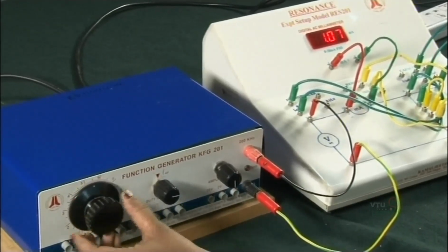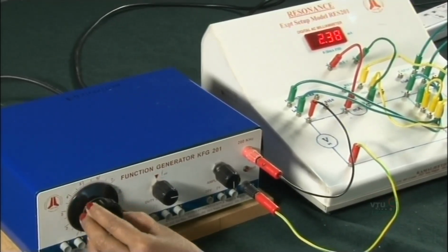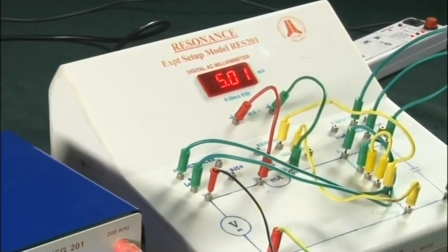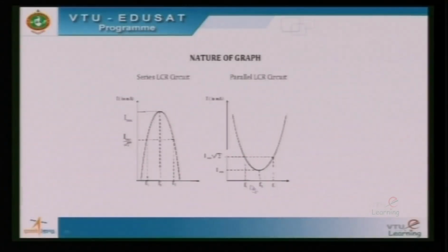As you increase the frequency, you observe that current is again increasing and reaching maximum. So, the characteristic graph as seen shows an initial decrease in the value of I as the frequency is increasing, because the circuit is more capacitive initially when all the components are connected in parallel, then reaches a minimum at which XL is equal to XC. Then onwards the circuit is more inductive, hence current through the circuit increases. So, resonant frequency is noted from the graph.